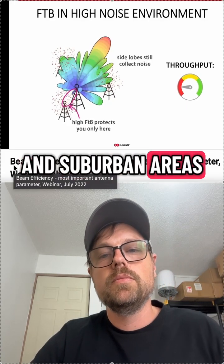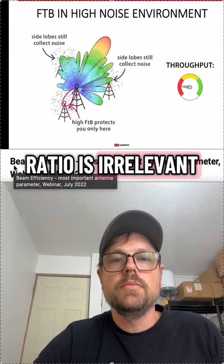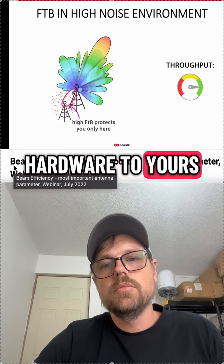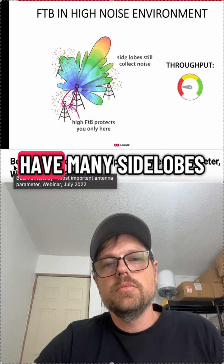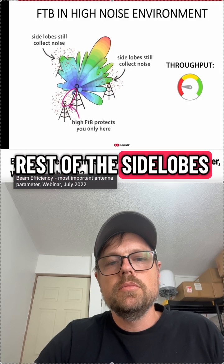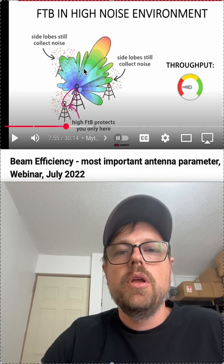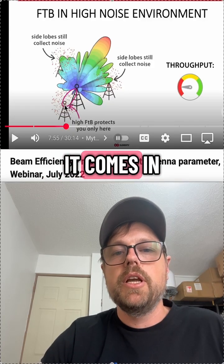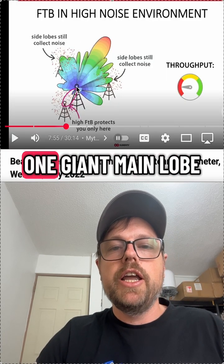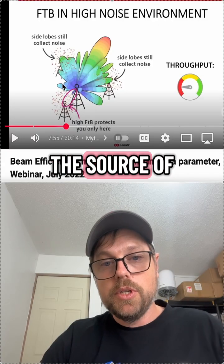So for urban and suburban areas with other wireless links in the neighborhood or even on the same tower, front to back ratio is irrelevant. These other links may be yours or competitors'. Either way, they're using very similar hardware to yours, meaning their antennas most likely also have many side lobes that create noise, receive noise, and anything in between through the rest of the side lobes. So again, we're seeing noise coming from the side lobes. Magically, there's no noise in the main lobe. But noise comes in the side lobes, it comes in this back lobe, and it also comes in the main lobe. If you were to shape all of these into one giant main lobe, maybe you're going to have better noise resistance, maybe not. It just depends on the source of the noise.